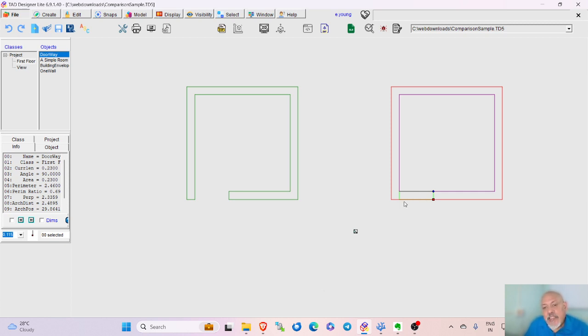So now what happens is, if I extract the area of the envelope, and from that I subtract this particular room and then this particular doorway, I can get the area of this wall, which is what you get here also. Here you get it because you drew this polyline, and in one shot you get it. Here you have to do a very tiny little bit more calculation, and it'll tell you the area of this wall here also.